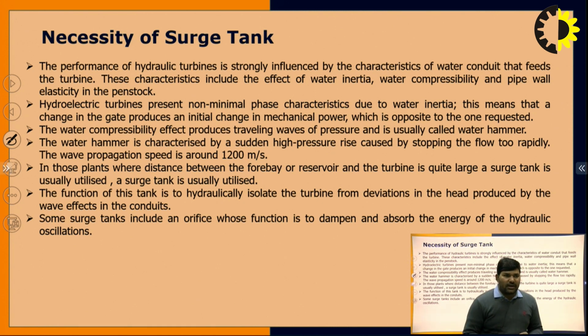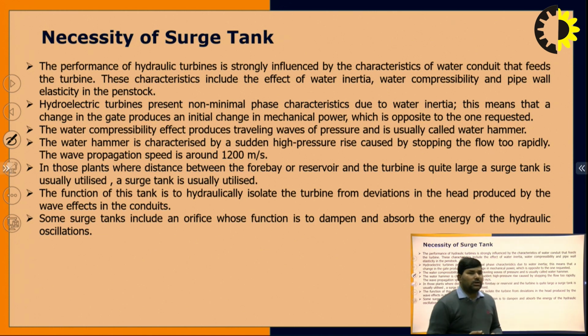produces an initial change in the mechanical power which is opposite to the one requested. And the water compressibility effect produces traveling waves of pressure, usually called water hammering.